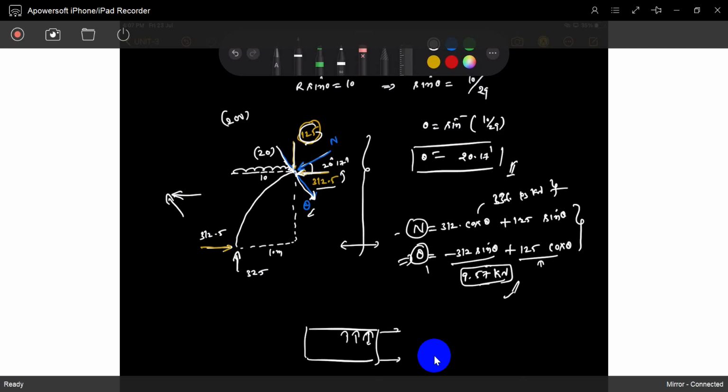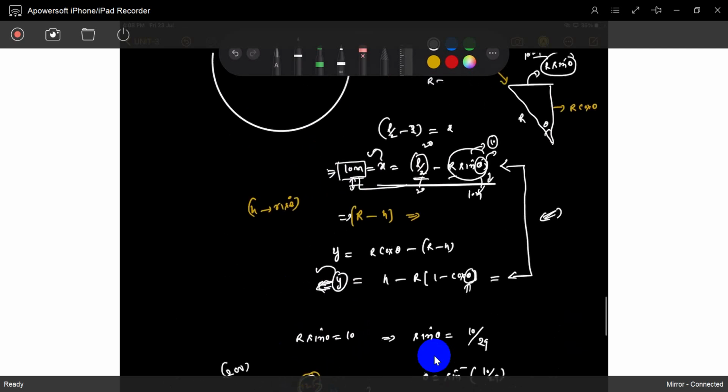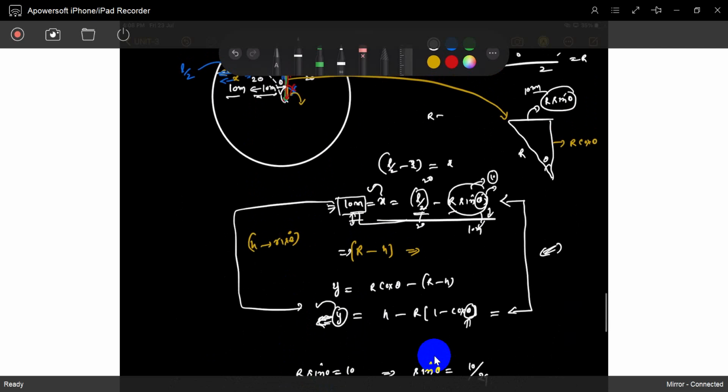So now you will solve any type of problem: three hinged arches, parabolic arch, symmetrical arch, semicircular arch, or segmental arch. How to find X and Y, I will explain here. Now you can solve any problem, find the bending moment at any section, and also find the normal shear and radial shear. That's the end of the story of three hinged arches, moment and shear force calculations.